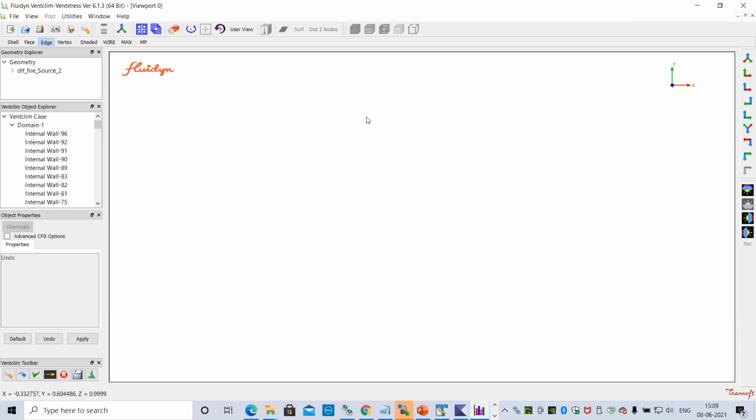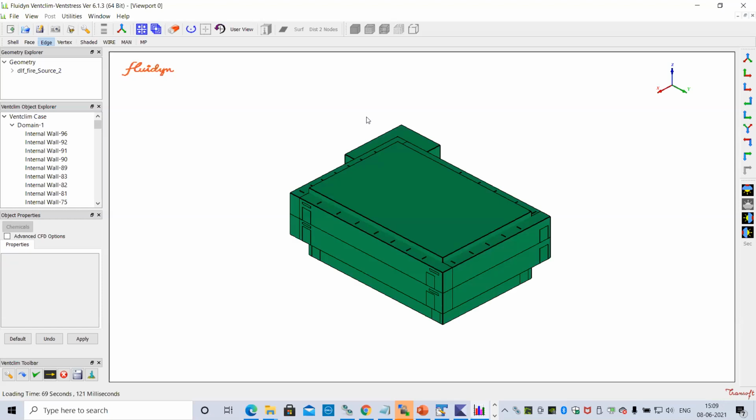Another one is which would be the better boundary condition, heat source or heat flux? If it is through a wall, then the best condition is heat flux. If inside the domain there is no boundary condition defined, and we didn't consider any partition over there, then we can go for heat source as an element-based input. Thank you, sir. You can continue.